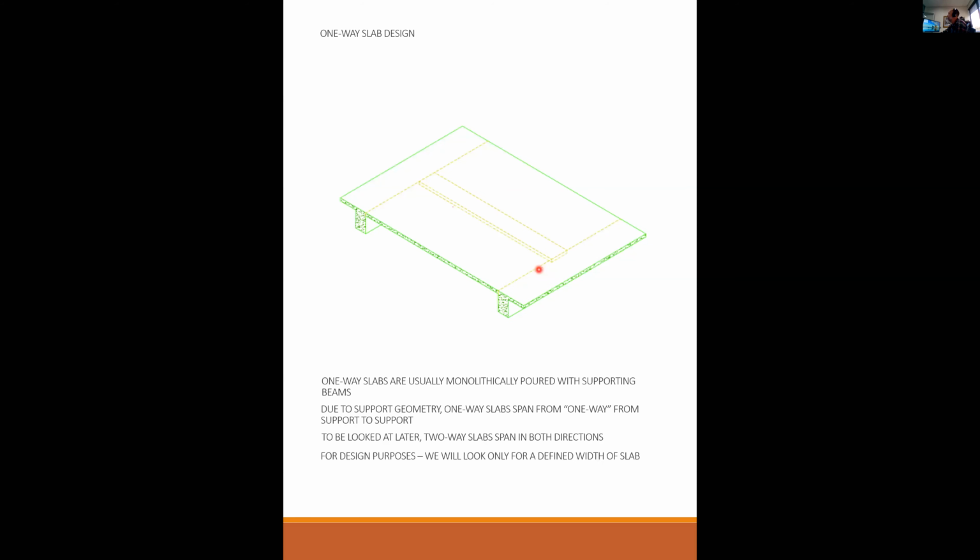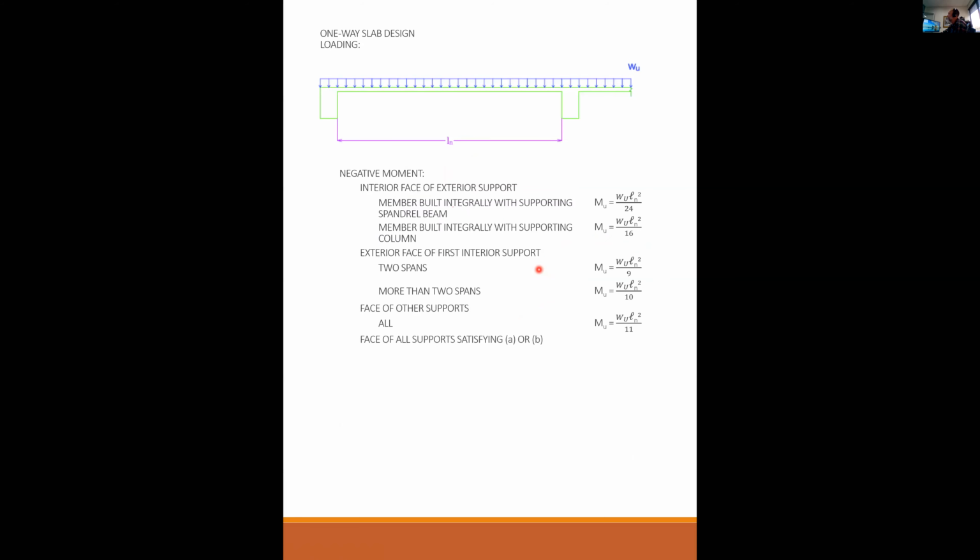But you need to be sure that you have a minimum amount of steel in there so that when the slab does crack, it doesn't crack horribly. It really is more of an aesthetic situation than structural, unless it cracks really, really bad. Typically, in a concrete slab, due to shrinkage, it will crack. And as long as you have a minimum amount of steel in there in both directions, the cracks will be controlled by that steel.